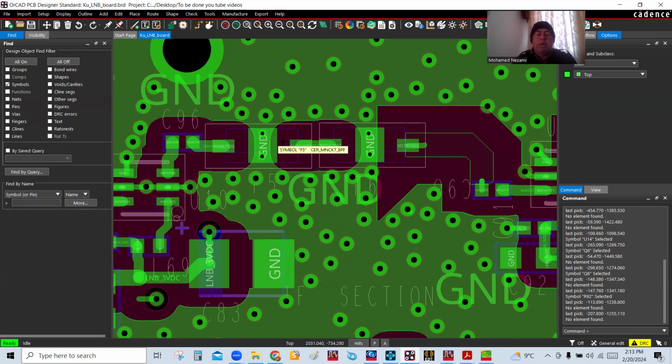These are two filters and they are 75 ohm filters, not 50. The reason they were made 75 is because a lot of the LNB IF ports are 75. In my case, it was 50. So I added an LC section at the input of these to match them to 50 ohm. And some might say, why go through that hassle? Well, because that device is nice and I had to use it. So I figured I could do an L section match from 75 to 50 and use it because of its neat frequency response and its size.